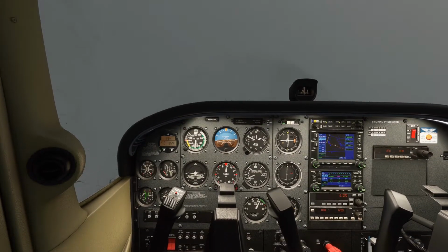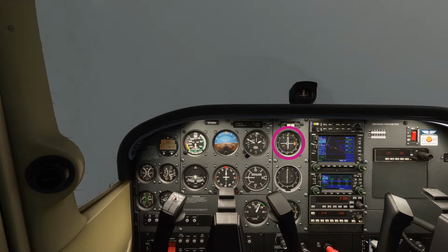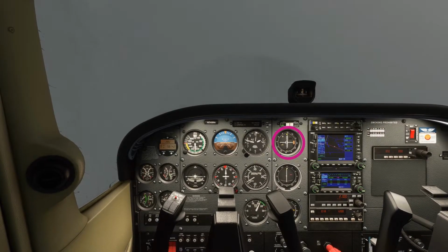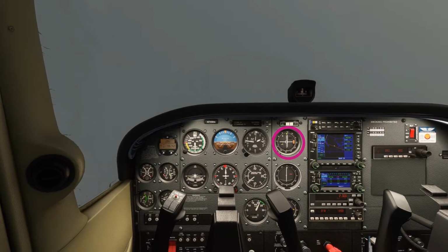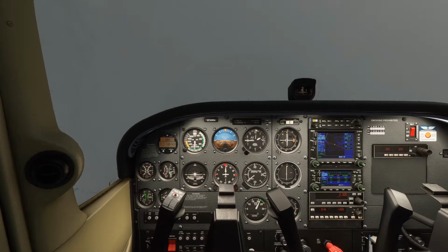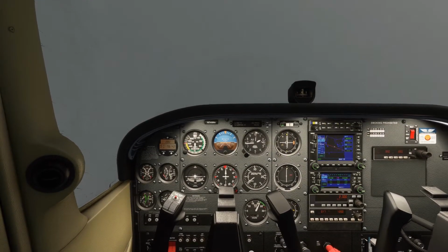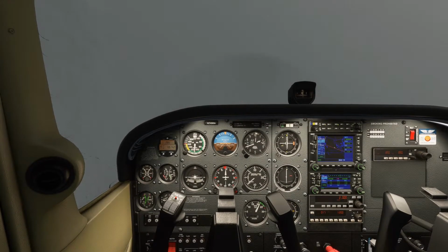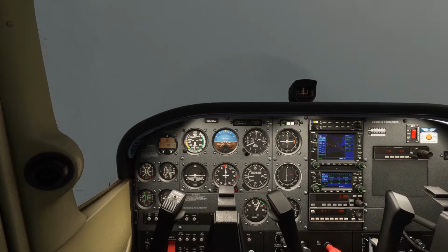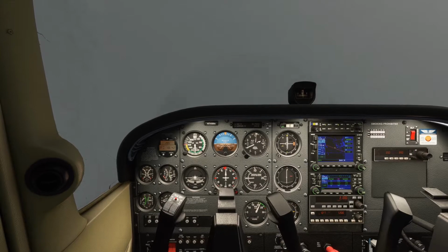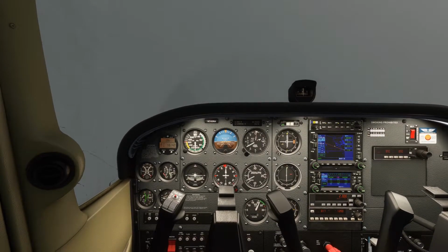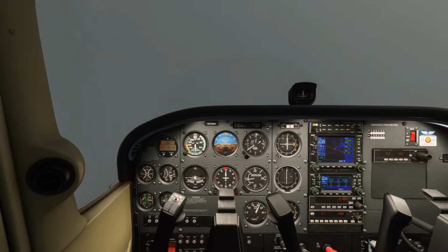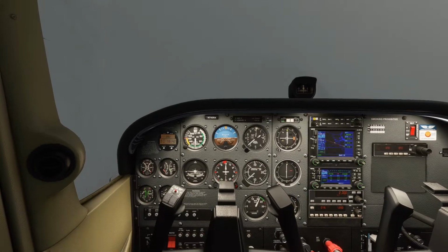You're slightly left of the track now, so I'm going to just make a turn to the right slightly just to re-establish that course. So keeping the scan going, attitude indicator down to the DI, making sure that heading's sensible. Up to the attitude indicator, across to the altimeter, making sure that we are staying above that 1600 feet for Maina. It's 2.9 miles to go, so there's no need to come down too aggressively. Attitude indicator across to the OBS and CDI there, which is just coming back in now by the look of it.